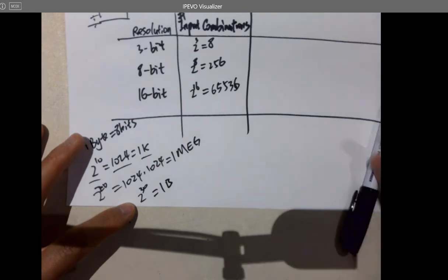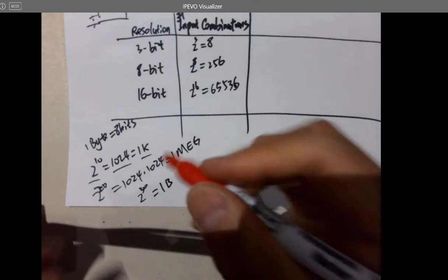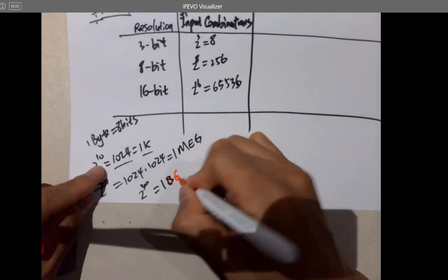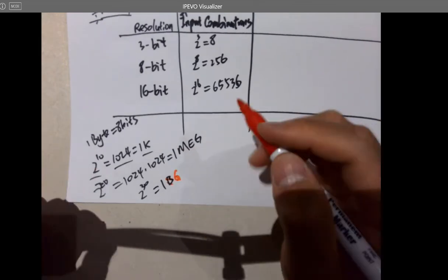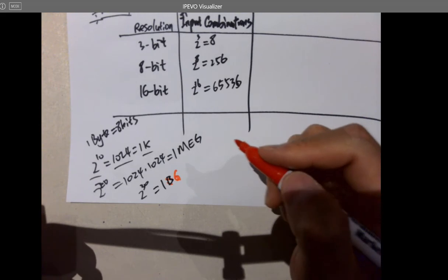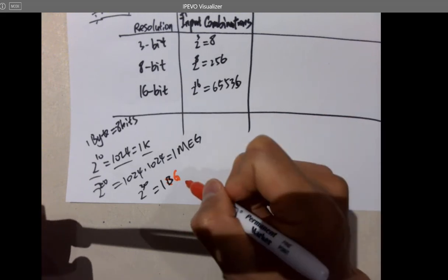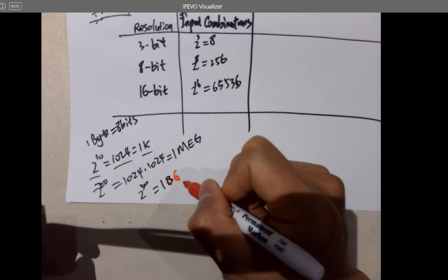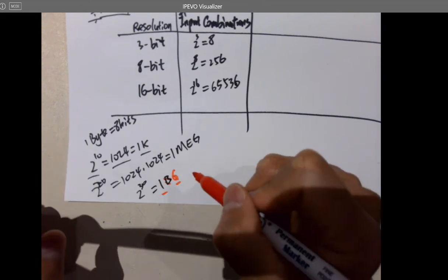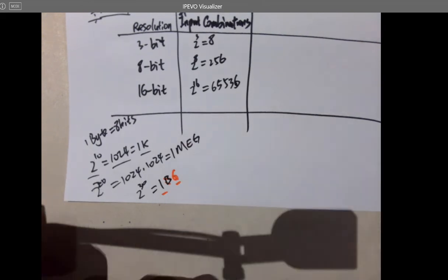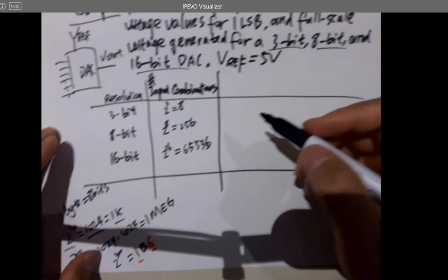We don't use billion here. What do we use? Giga, 1G. It also applies to LTspice, I guess. If you put a G there, they are going to treat this one as 1 gigahertz. Okay.